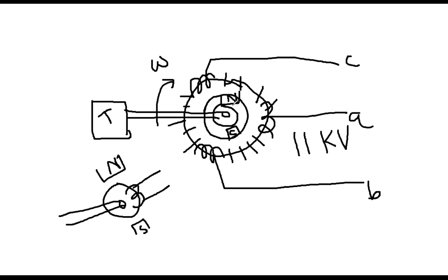Therefore, in this case, what is happening? The magnetic field is moving, but the coils are static. In the case of a DC generator, it produces hardly 1 kV, hardly 1000 volts DC, because this is for small scale application. That's why even though it rotates, it is not that dangerous. It is not a three-phase system, and there are not so many coils here. That's why traditionally the armature rotates in this case and the field remains static. But in the synchronous generator, because of the high voltage, the insulation issue, and the coil deformation issue due to centrifugal force, the armature remains static.